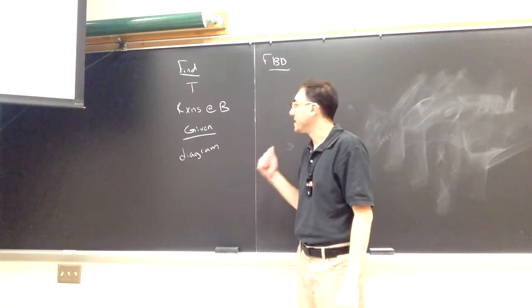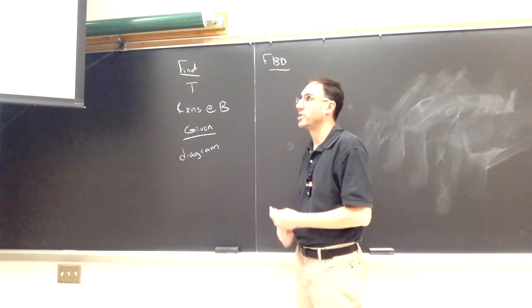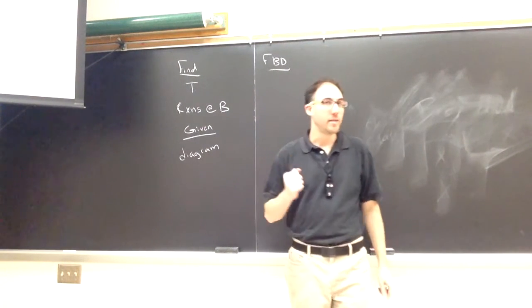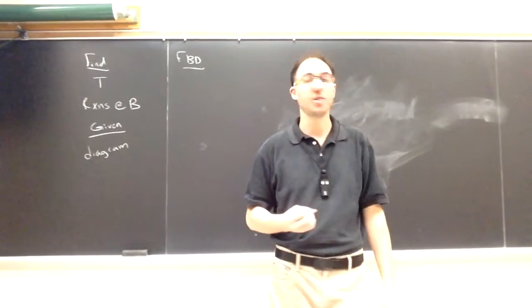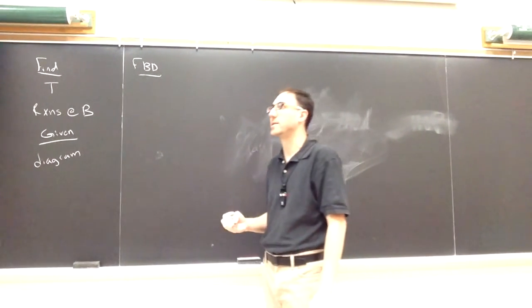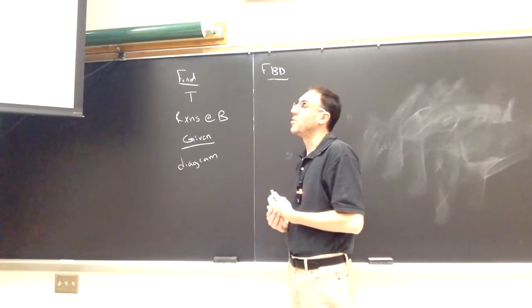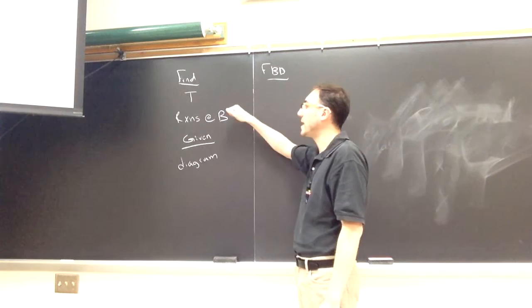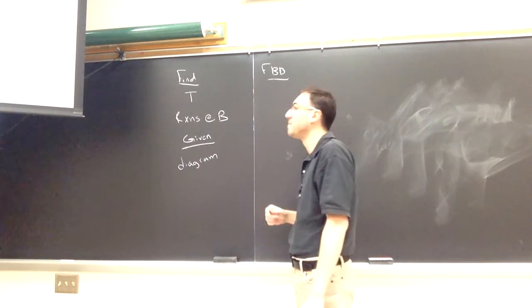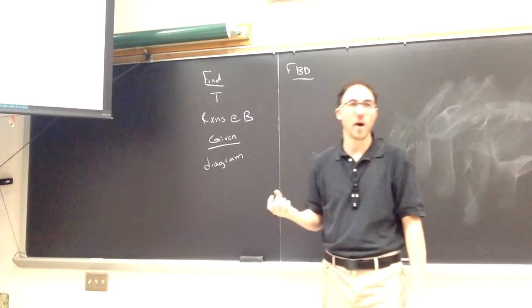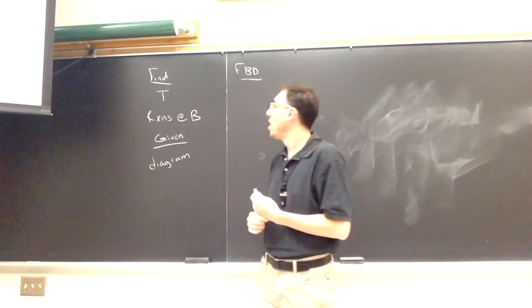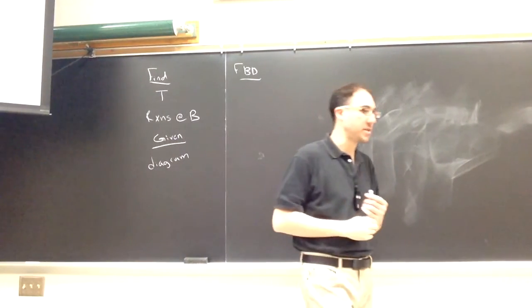So to find the tension in the cable and the reactions at B, in the free body diagram step, we need to choose what is the object we're going to isolate from its connections, from its supports. So in this case, if we want to know the tension T and the reactions at point B from the square shaft that it's on, what should our object of interest be?